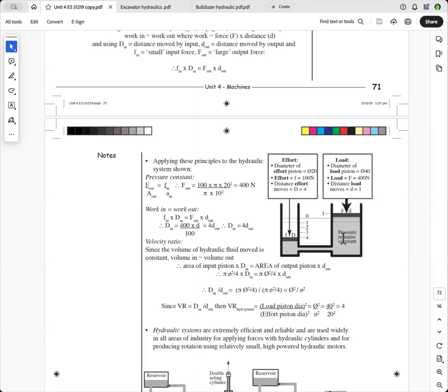But as soon as disc brakes started coming in, you had to have some means of reducing the force, allowing you to apply less force, but the brake booster will boost up the force. Okay, so I hope you've got that, and that's as a result of the conservation of energy.